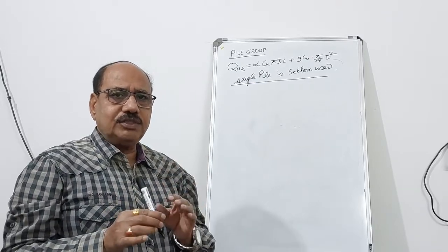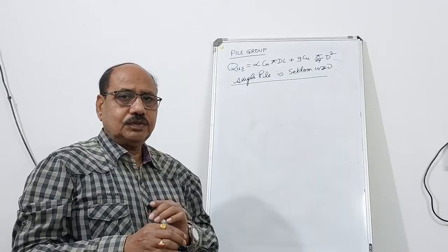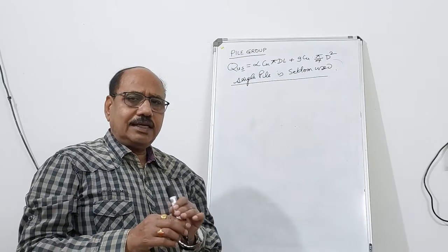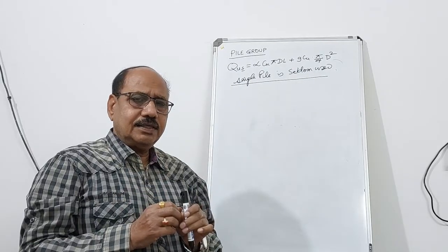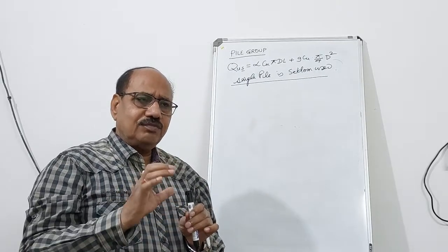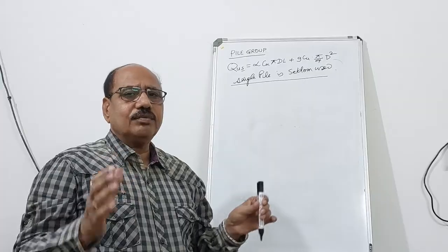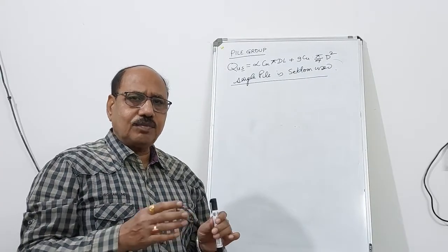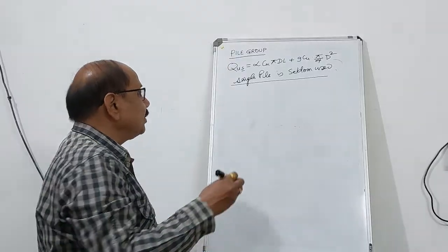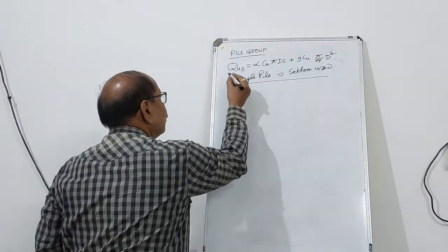Therefore, piles are always used in groups, so that even if there is an eccentricity, the flexural forces will get distributed over the number of piles.